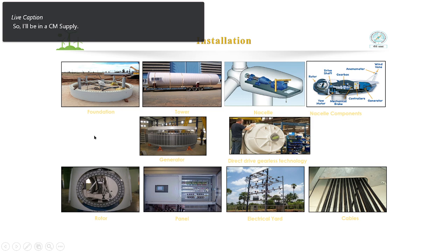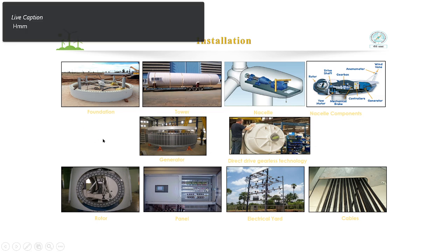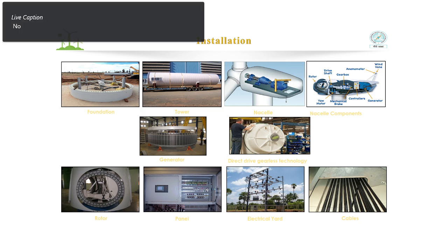This foundation installation, normally most of the towers are tubular, except a few, like the hybrid Suzlon towers. Towers can also be hybrid. It can be pre-stressed concrete. Windworld or Enercon, they have pre-stressed concrete towers. Are you aware of it? No, I heard of hybrid, but normally concrete towers are being designed, right, sir? Yes, but all installed. Windworld is original Enercon.